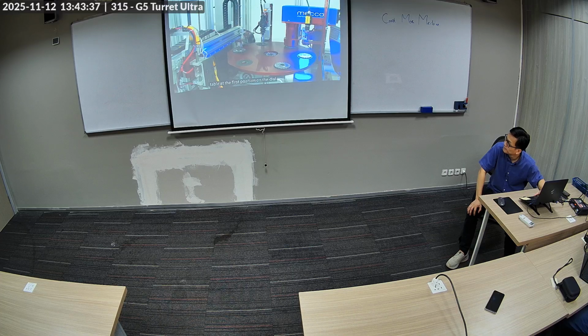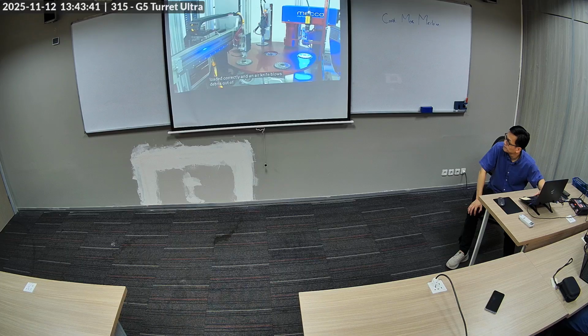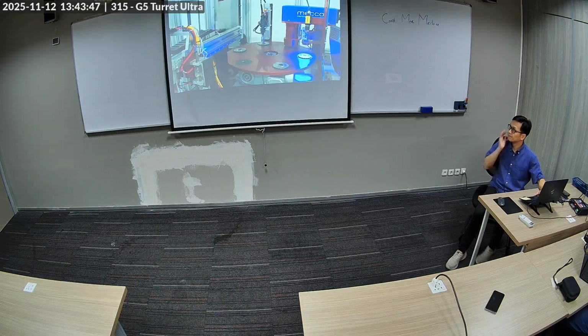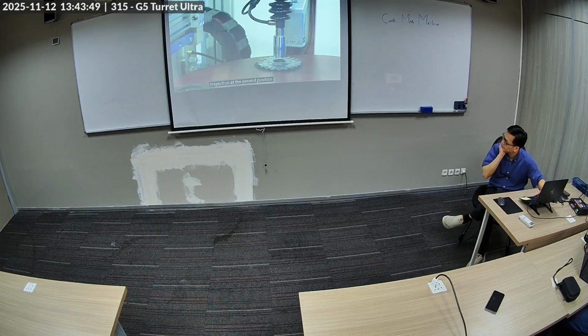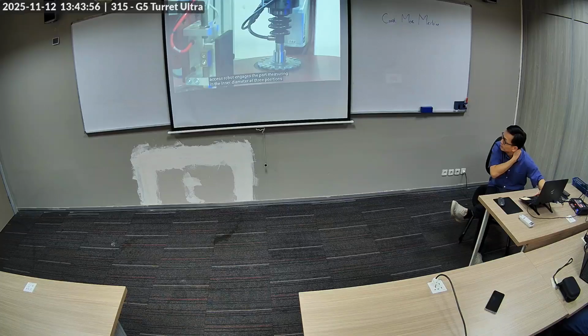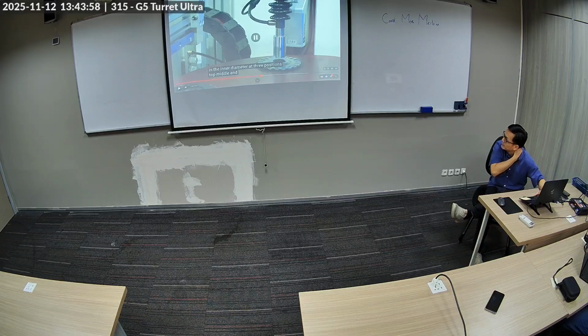At the first position on the dial, a sensor verifies that the part has been loaded correctly, and an air knife blows debris out of the inner diameter of the part, cleaning the part prior to inspection. At the second position on the dial, an air gauge mounted on a single-axis robot engages the part, measuring the inner diameter at 3 positions, top, middle, and bottom.